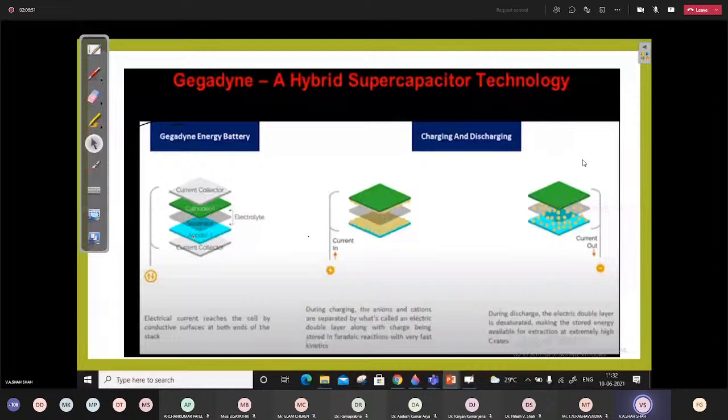So this is 12 to be connected in series, and you can find the current also, because the discharge per cell is 5 ampere. The total current with respect to this peak power will be this divided by 48, which will give you 86 ampere. So this current has to be supplied by the battery.